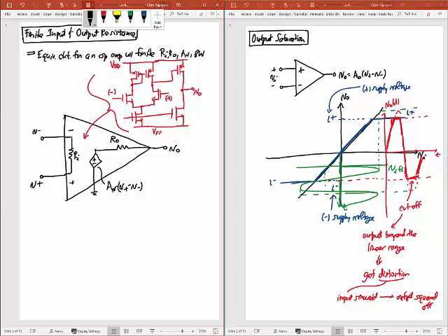Okay? I need to do one more thing to this op-amp to model the frequency response. And so how would you model its frequency response? I already have the finite gain by just saying A sub V there. But if I wanted to add something to give this an op-amp-like frequency response, what would I do? Yeah, I'd add a capacitor somewhere. Where would I add that capacitor?